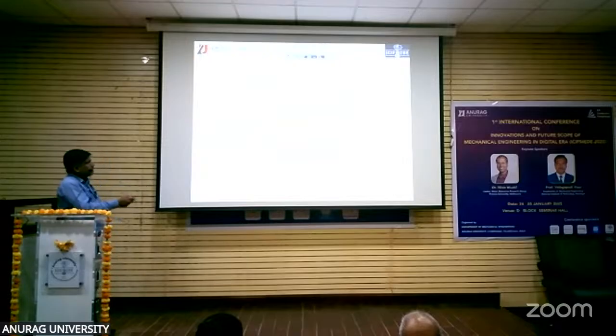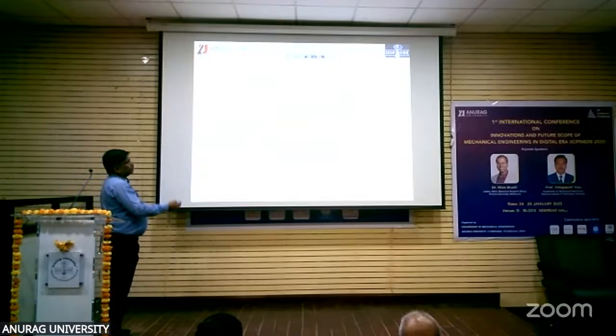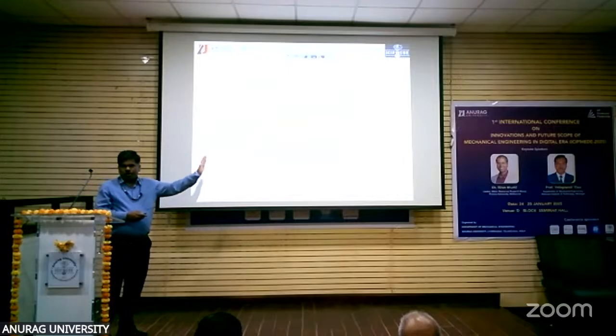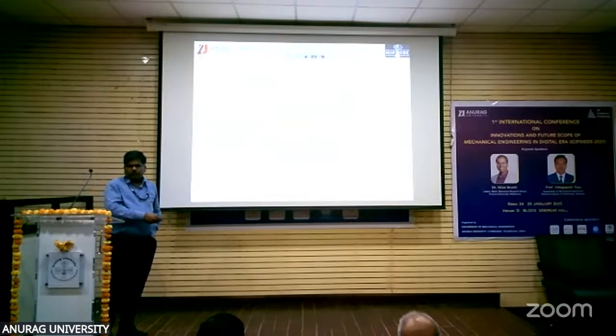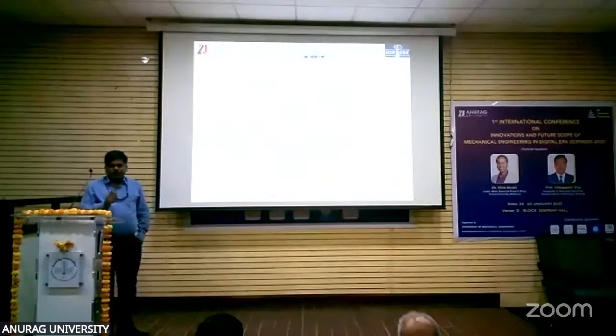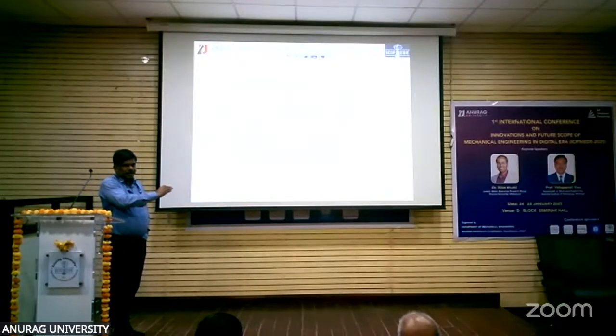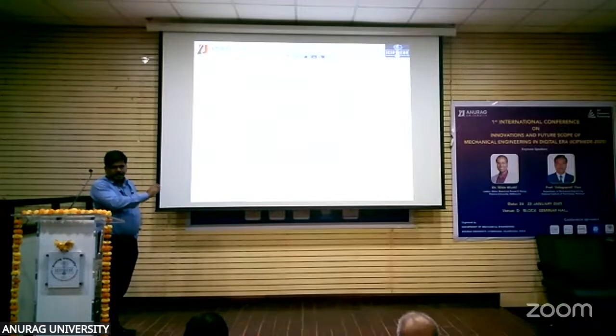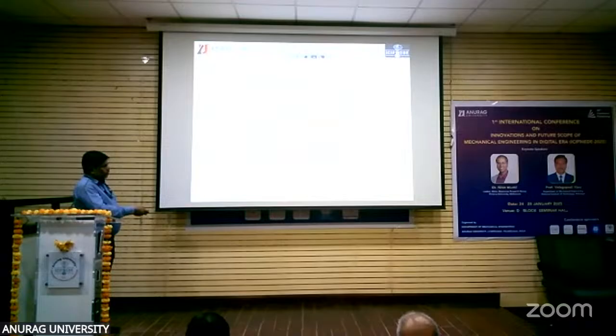Next, you can give the input for table number 3. That is for designing purposes. Suppose you want to design the boiler, then what is the fluid bed velocity, the fluid bed temperature, those kinds of inputs can be given in the table. Just for our convenience, the data is divided into 3 categories, so it is easy for us to look at these things. Once we are okay with this data, we can close it, go to the particular program, and run.